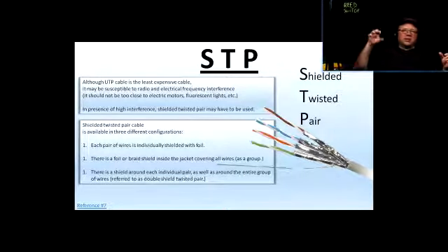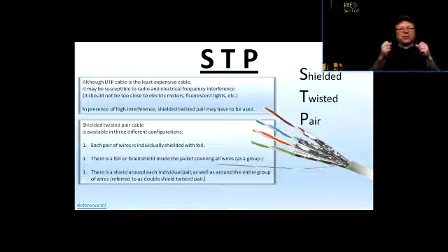There's a lot of interference, a lot of electromagnetic interference, noise, or whatnot. Then you need to have a shielded pair. So for the most part, you're going to have that shielded twisted pair installed in that kind of environment.